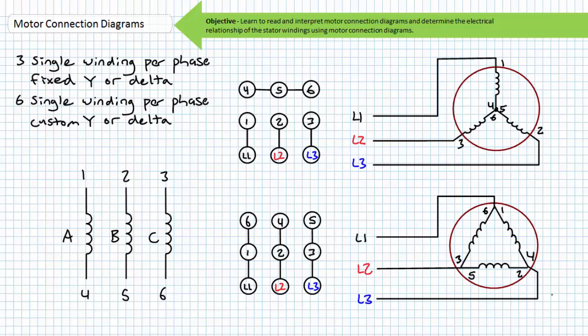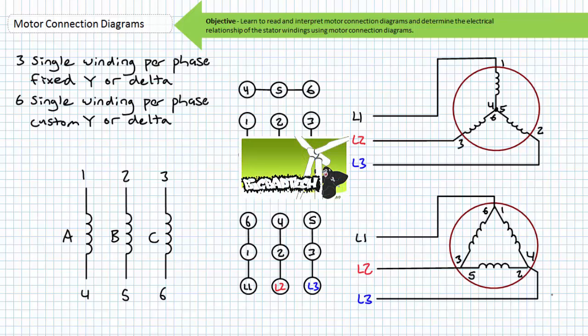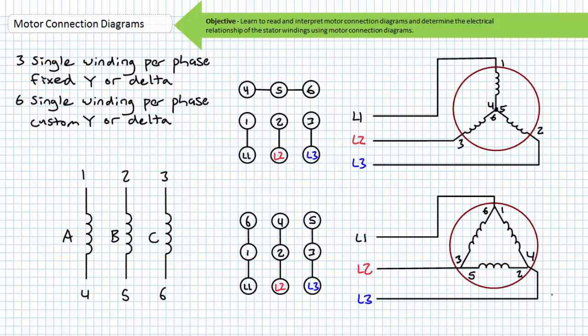Once the motor has achieved a given speed, counter-electromotive force, sometimes known as CEMF, a concept discussed in the electromagnetic interaction lecture, will be greater, and then full line-to-line voltage can then be applied in a delta configuration. The staged application of voltage to the motor windings ensures inrush current doesn't place an unnecessary burden on the electrical supply system. We'll discuss this and other methods of reducing inrush current in later lectures.